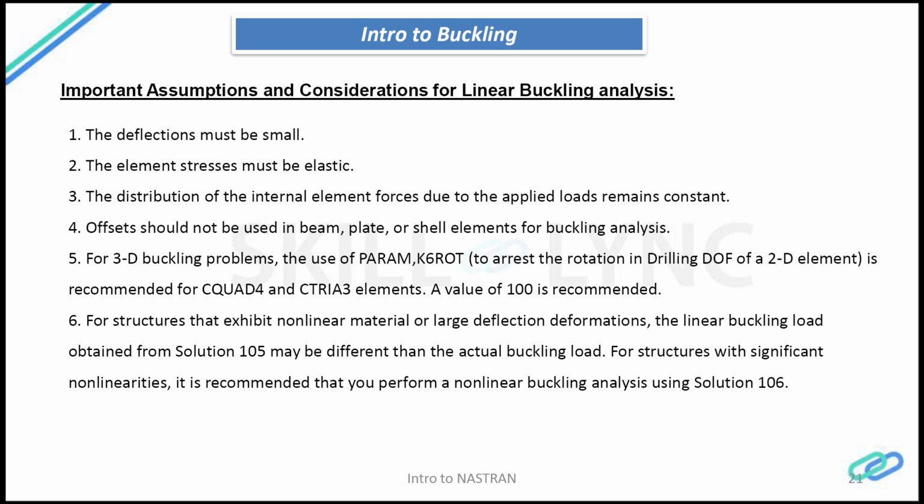And another thing is, for any structure that is exhibiting nonlinear material or large deflection, what we could do is run the structure first for the nonlinear analysis, just to understand how the structure behaves.